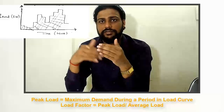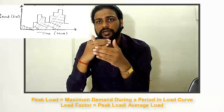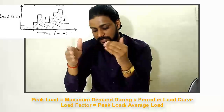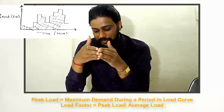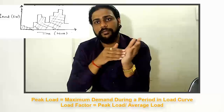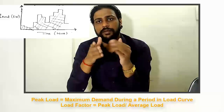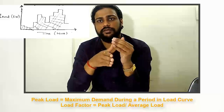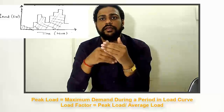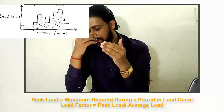Demand is how much is drawn, and when you plot your demand with time, you get the load curve. In that load curve graph, you will have the peak, which is known as the peak demand. And the demand factor is the maximum demand divided by the connected load. So the maximum demand, that was my peak load, divided by my connected load. In the example I gave, my peak load was 1500 but my connected load was 2000. So 1500 divided by 2000 will be my demand factor, and this will be less than 1.